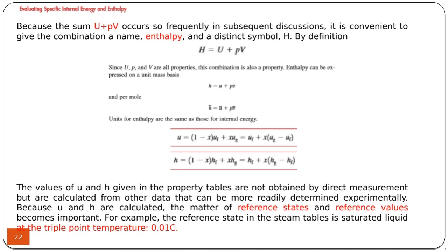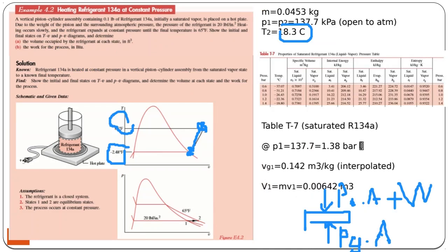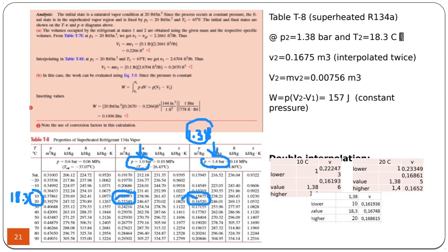By the way, it's also asking you the work done during this expansion because the piston is moving up in a closed system. If there is a piston cylinder system, the work done is equal to the integral of P times dV. And because in this case P is constant, it's free at the top, so you can see that it's expanding freely.